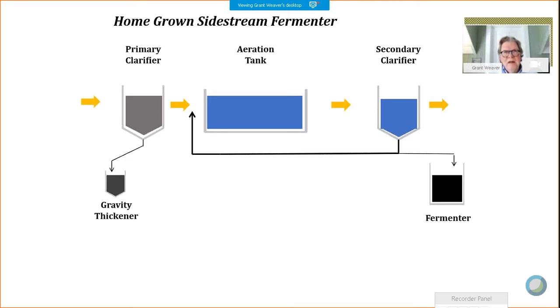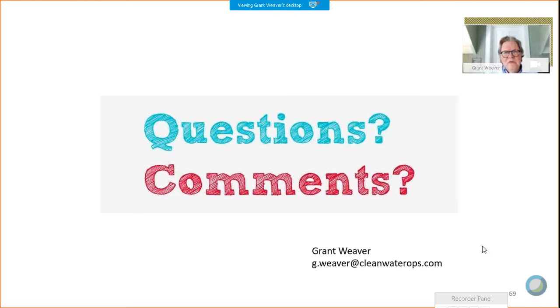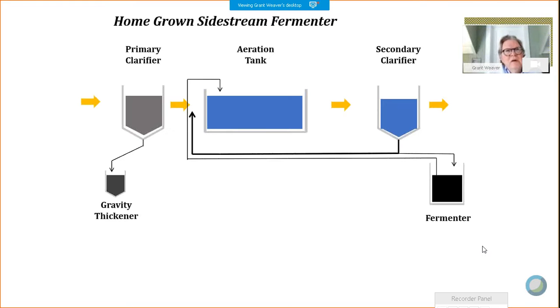If it's a holding tank, or an aerobic digester, we want to find a spot in the pipe, some kind of a vessel, where we can let the sludge sit for 2 or more days, long enough to get septic, long enough to create volatile fatty acids, long enough for any phosphorus removing bacteria that live in that waste sludge to eat the volatile fatty acids, and then pump some of that back into the aeration tank.